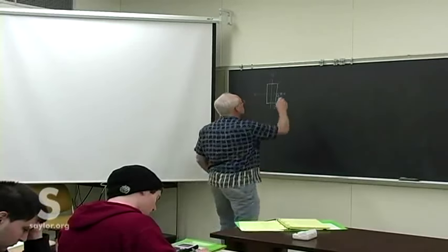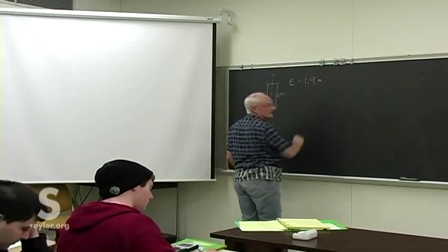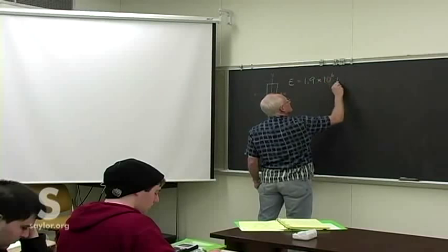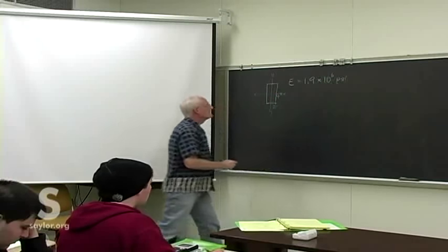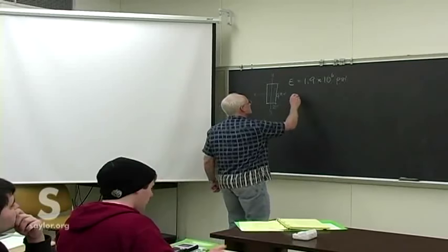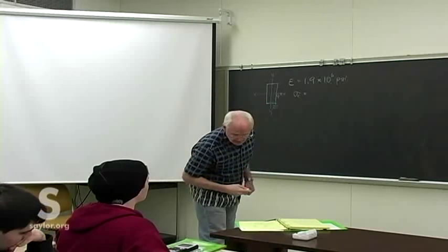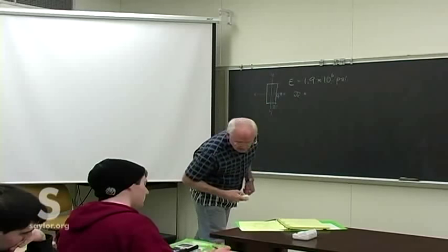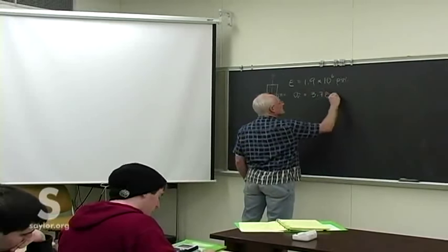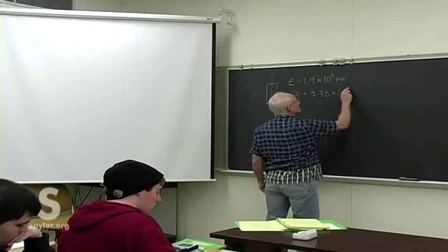We'll use Douglas fir, which has a Young's modulus of about 1.9 times 10 to the 6th psi. Good thing it's in psi. We'd hate to have to use wood that has values in SI units. Allowable stress of 3.78 times 10 to the 3rd psi.